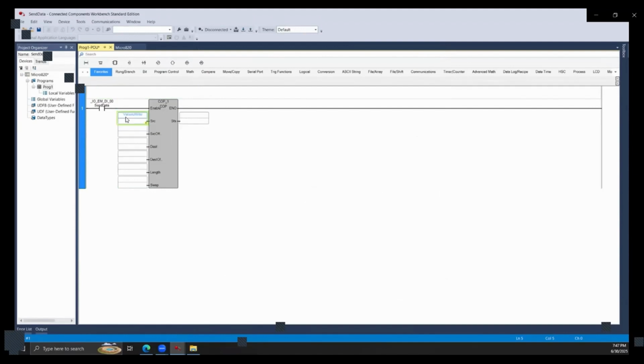So this is the source, value to write, that is UDINT, a 32-bit unsigned double integer, and source offset is set to 0, and A underscore data is the destination data, and destination offset set to 0, and the length of A data is set to 4, and the SAP is set to 0.